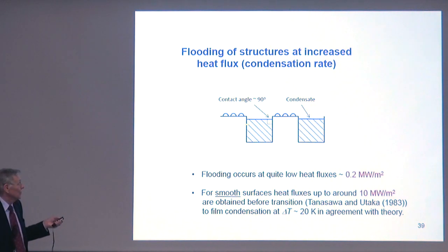This is a stable contact angle. The grooves are filled, and you've got a much reduced area with dropwise condensation on there. Flooding occurs, and the heat transfer coefficient falls at this sort of heat flux. Tanasawa went up 50 times higher than that on a smooth surface before transition to film condensation.